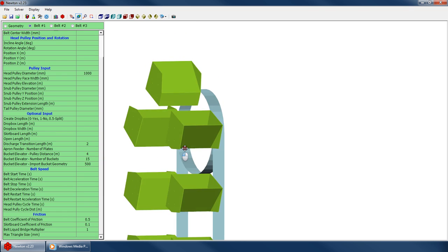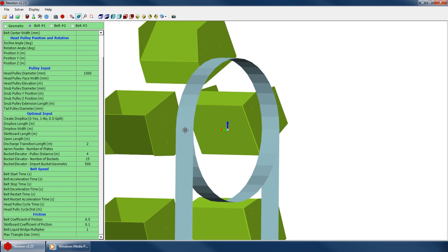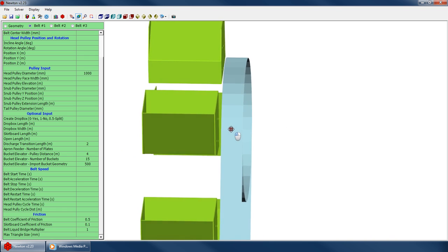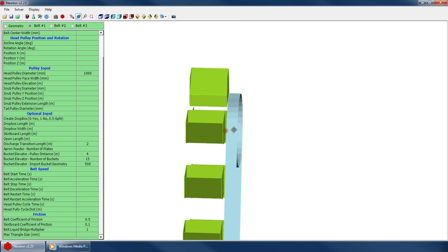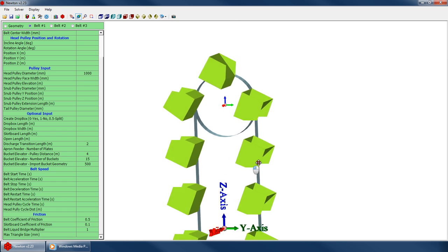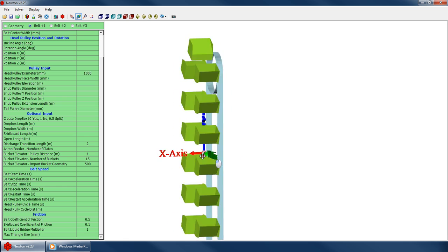So for this specific CAD file, the origin has to be basically right exactly here, right next to that bucket. It's outside the surface of that bucket. So if I was to redefine the CAD file and put the origin right on this back face, it would shift the bucket over and it would be right attached to that track.